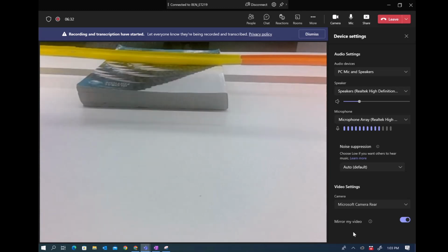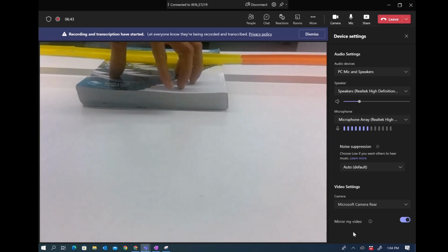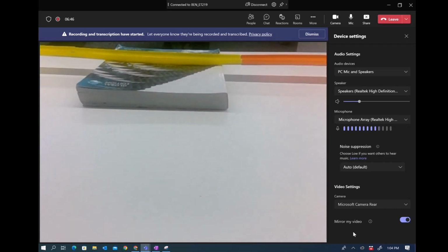These extra supports create extra reaction forces, and that extra reaction force adds complexity to our calculations. Here we have 2 reaction forces because it's a pin support, and a reaction force here, third, and you have 4 reaction forces but 3 equilibrium equations. We can't solve it using the conventional methods that we learned from week 1 to week 7, right? We have done many examples on cantilever beams and simply supported beams. Now, this week, if I add an extra support to the simply supported beam, how are we going to solve it?